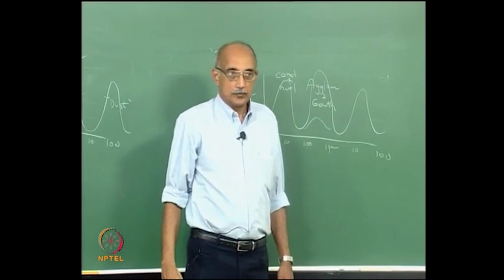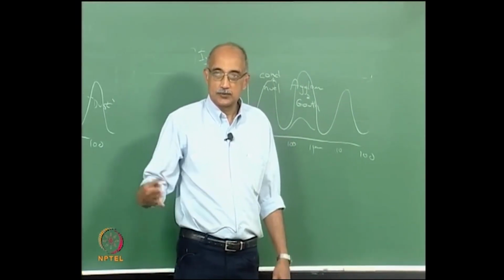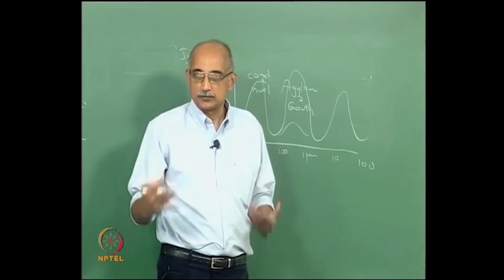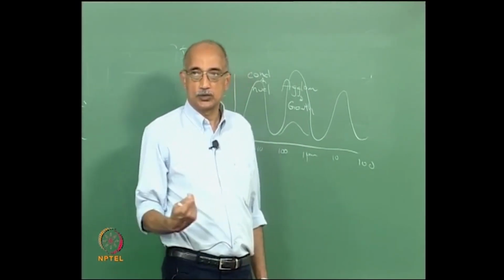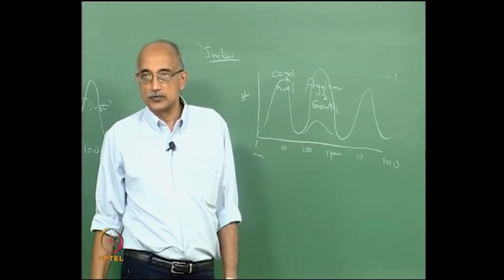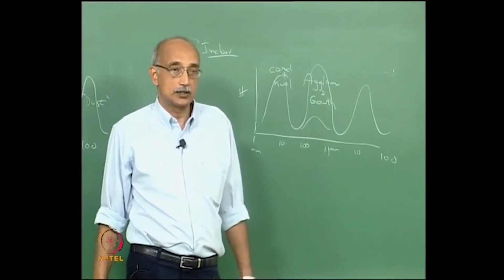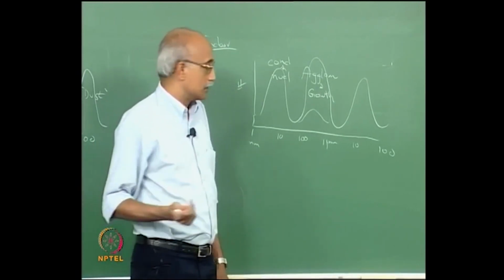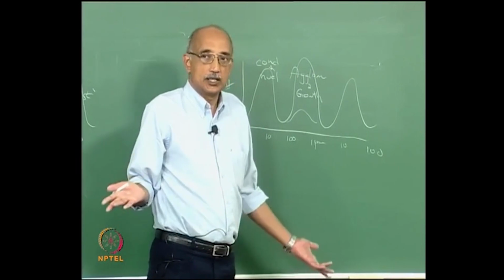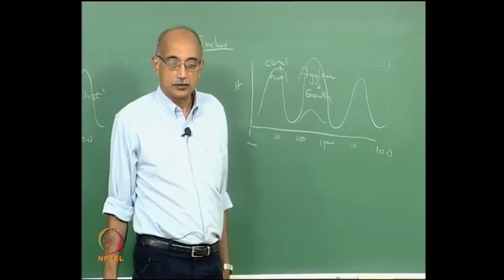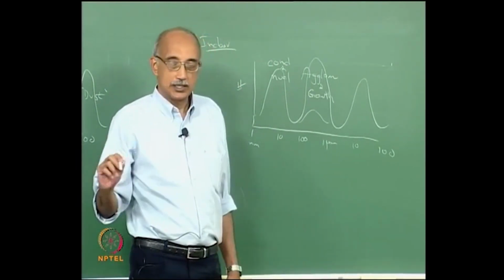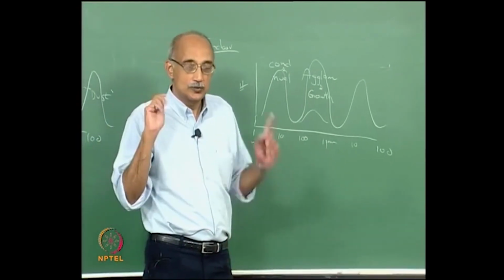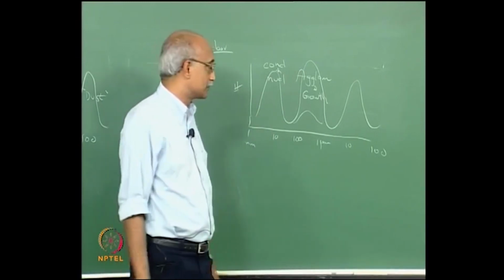This room, for example, just in terms of clean room classes, it's probably about 1 million. And just to give you a perspective, if you actually took a particle counter and measured particles in this room, you will find there is at least 1 million particles per cubic foot that is half a micron and larger. Even though none of them is visible, you would think that this is a clean room, but it's really not. It's a clean room, but that's different from a clean room. It depends on whether you write it as one word or two words. Okay, clean room is something that is a very special thing.